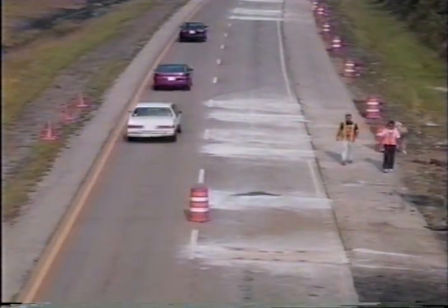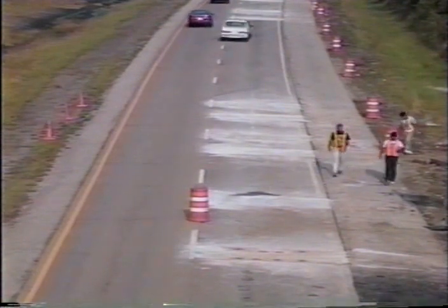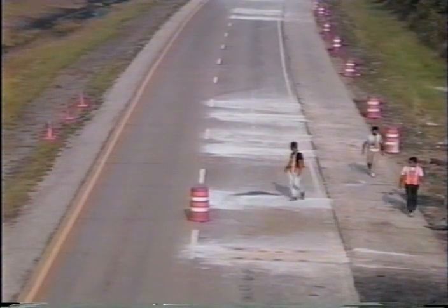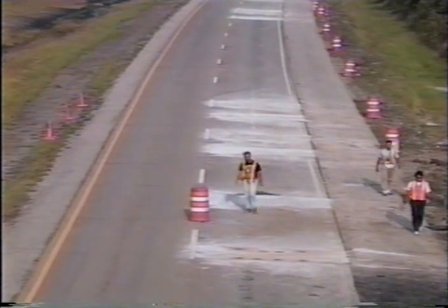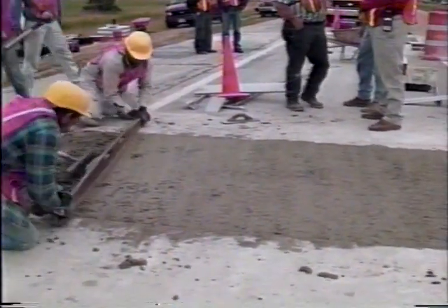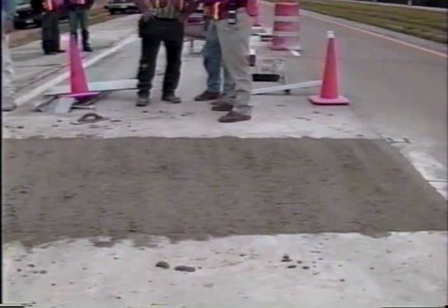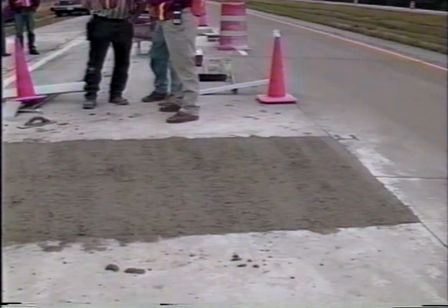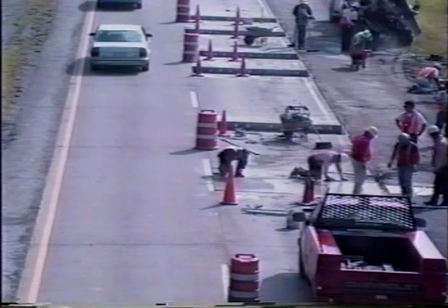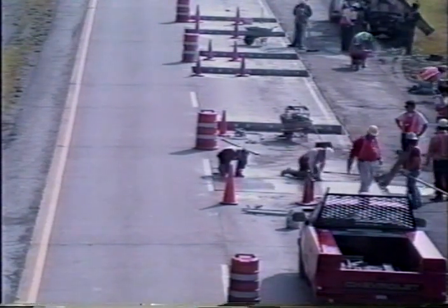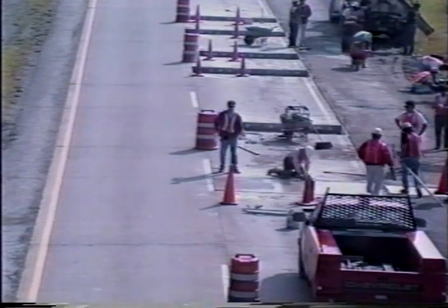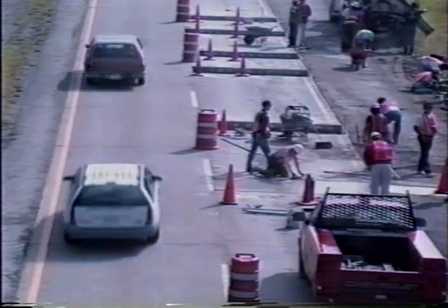Many recent developments in concrete materials and processes allow new and repaired pavements to be open to traffic at a very early age. Because new mixes produce rapid strength gains and high early strengths, concrete has become a more cost-effective repair material. As a result, materials and design engineers working together in pavement management can address the specific problems of the pavement and still minimize closure times and traffic disruption.